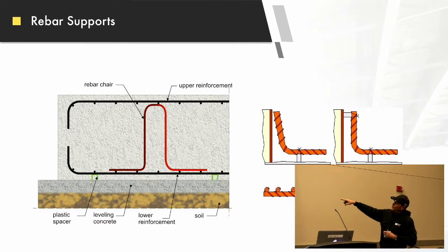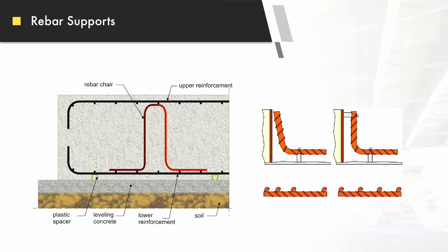In between mats of steel, like on approaches, not so much on decks, but footings, abutments. A lot of times the contractor will try to stack dobies in there. That's unacceptable. They'll try to stack chairs on top of each other, unacceptable. They need to be using rebar chairs that are bent to the proper distance. A lot of times they'll try to go and makeshift some, bend them. Again, then you have rebar in there that's not coated that will eventually rust and deteriorate our structures.